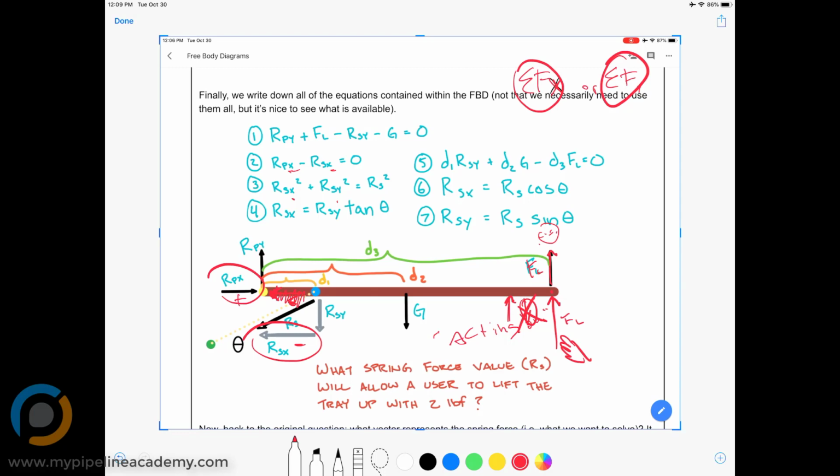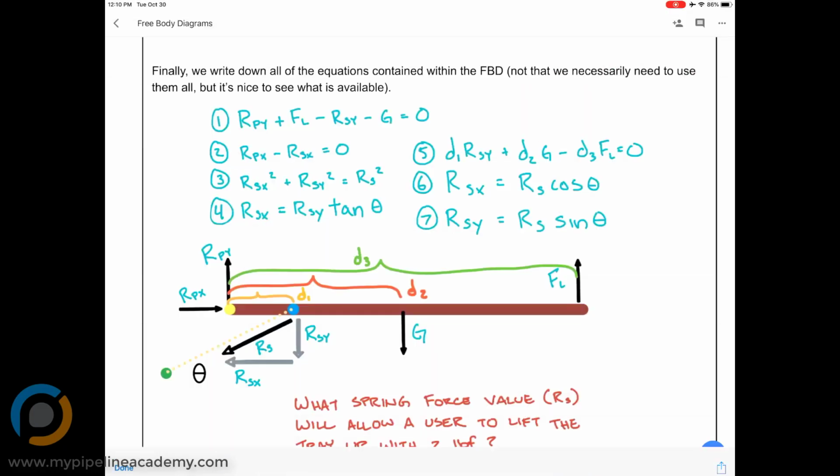Okay, so second equation. Assuming Fx equals m ax, that really rearranges to, with x origin 0, we multiply by m, so it cancels out. So really we just end up with 0 equals Fx, and 0 equals, very important, the minus sign, guys, don't forget that. So minus Rsx plus, because it's going to the right, Rpx. Is that what we had? Yeah, it's a plus sign over there. Okay, all right, so there's equation number 2.